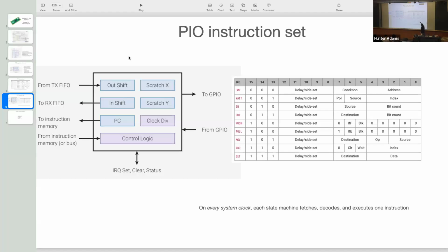There's a jump instruction. All that the jump instruction does is take the program counter, and rather than incrementing to the next line of code, it asks a Boolean question. It checks a condition. It could check a condition, or it could be unconditional. And it will jump that program counter to someplace else in the code that you specify.